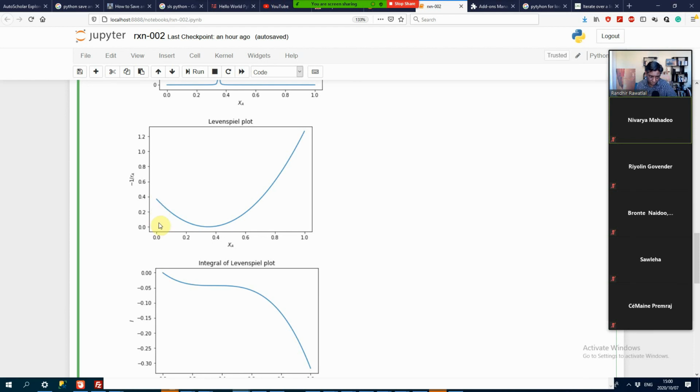That's because the CSTR is operating at its exit concentration. Think of a CSTR. It's perfectly mixed, and so the concentration in the CSTR is the same as the concentration at the exit point. It's not the same as the concentration at the inlet point.